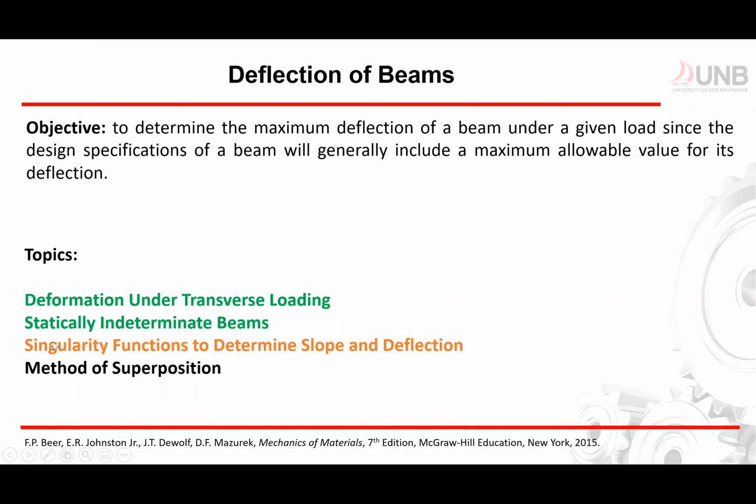Now for the second topic, statically indeterminate beams, the main objective is to calculate your support reactions. In this case, let's say you have four different unknown forces and you can only generate three equations. So it's not solvable, and you have to get another equation to solve your problem. You can use the second order differential equation or the fourth order differential equation, and use the boundary conditions to solve for your support reactions.